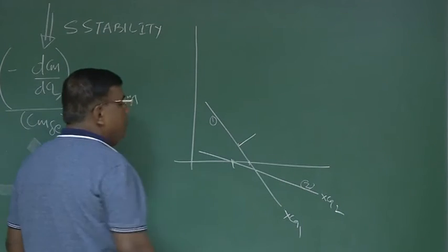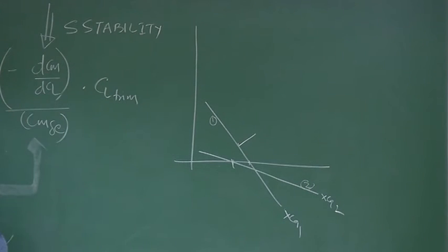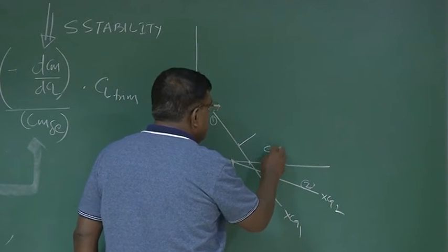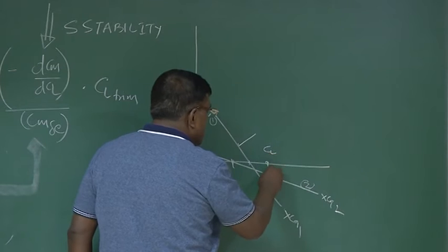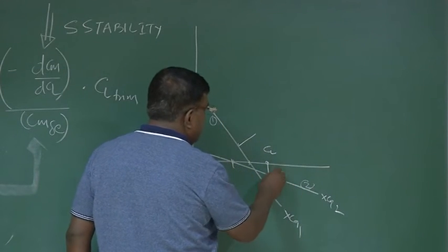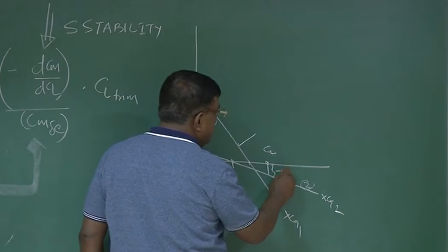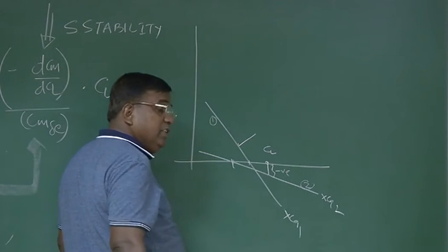Definitely, this one has more slope, more negative. So you could see that if I want to trim at this point, this configuration requires elevator deflection to neutralize this much negative pitching moment.